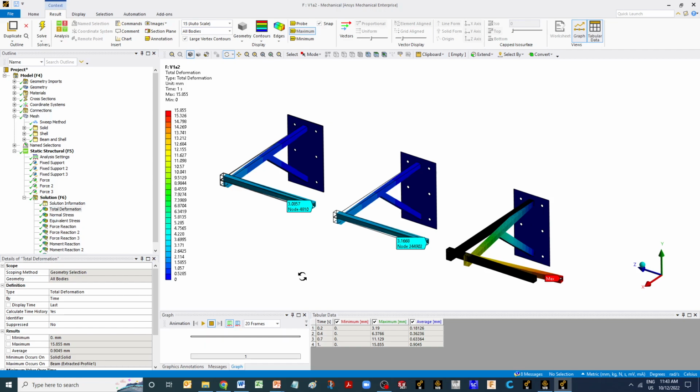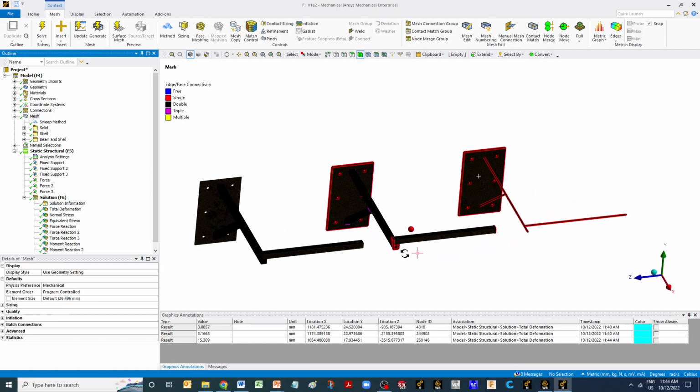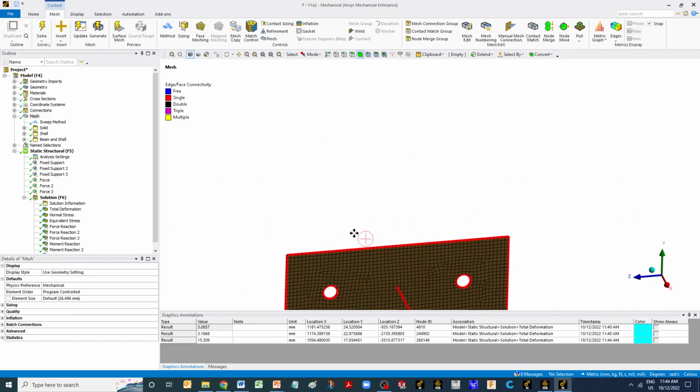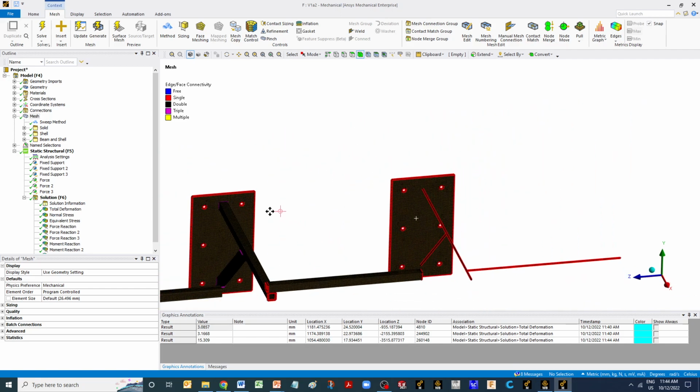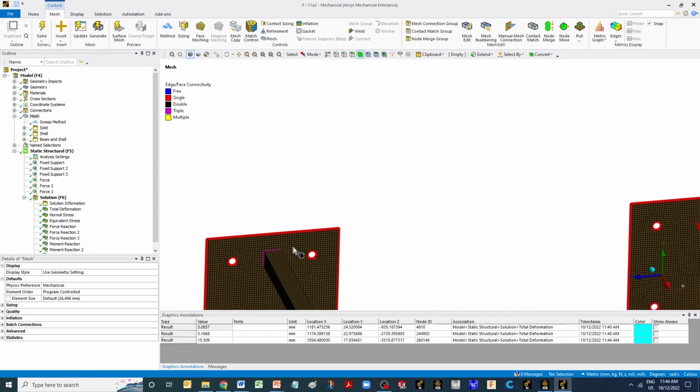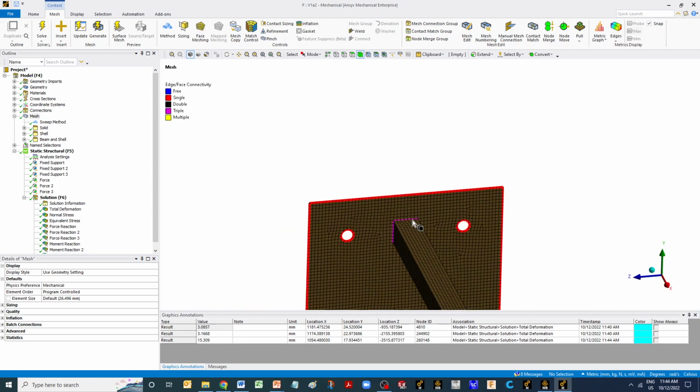If you recall, the major issue with that analysis, with the support plates, was that we were getting very large displacements in the beam model. So this is about 16 millimeters versus roughly 3 millimeters in these two models. And the reason I mentioned briefly was that the node sharing here is not reflective of the way the structure is connected in the actual physical